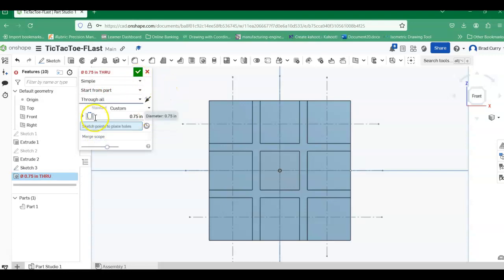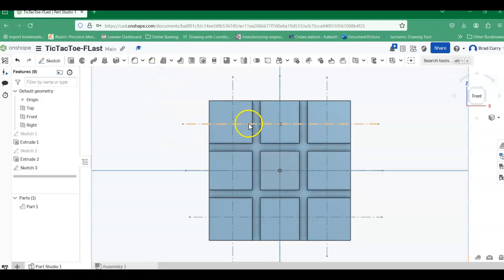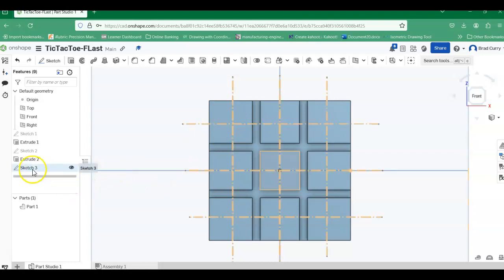And when I have this, let's go ahead and change this to 0.1875, a 3/16 hole. So we're going to make that. Now, when I come over here to my drawing, it doesn't let me put anything in here. Mainly because if I go up here where it's red, it says did not regenerate properly, no hole point selected. What that means is we need to go in and put points for it to select the hole. And this isn't that difficult to do.